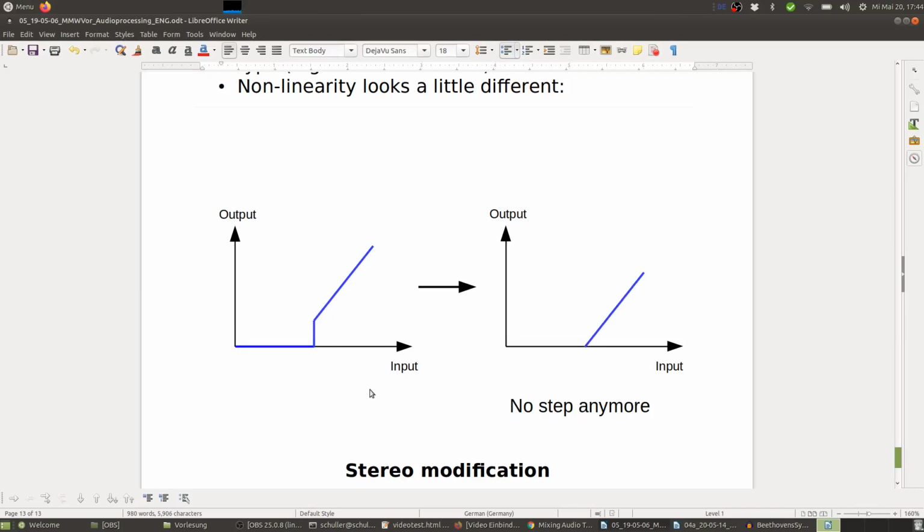Yeah, and this is used in image denoising. So the DCT is usually used for JPEG compression to basically ignore high fine details in images. And you can do the same for denoising. So when you have noise on images, it often appears as like the snow pattern, so it's often fine details. And then this nonlinearity again helps to remove those subbands which only have the noise patterns in them. So it smoothes more or less the image.